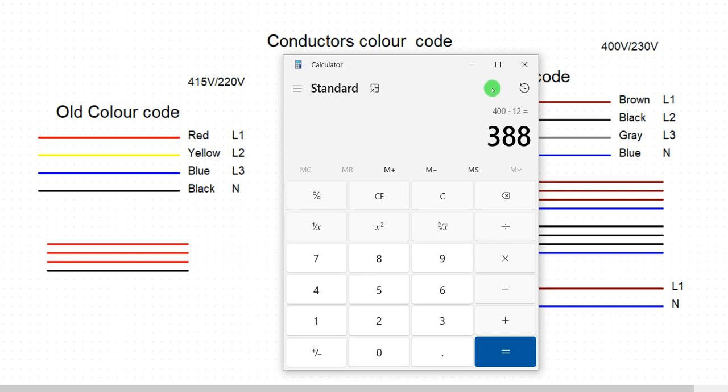All right. Now, then for lighting circuit of 230 volts. Okay, 230 divided by 100 times 3. So it's going to be 6.9. So when we are working with lighting circuit, make sure that your voltage drop does not exceed 6.9. Okay, so let's say we minus 6.9 from 230 minus 6.9.